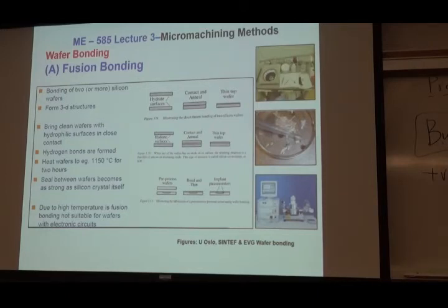You come in, you align them, and you put them together, hoping the materials on the top really are aligned. Remember, some of the features are 10 micron. If you're aligned by 15 micron, everything washes away. And it happens. If you're misaligned by 5 micron, you get a weird structure. So it's sensitive, but you get trained to do that.